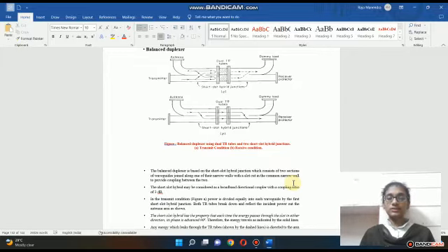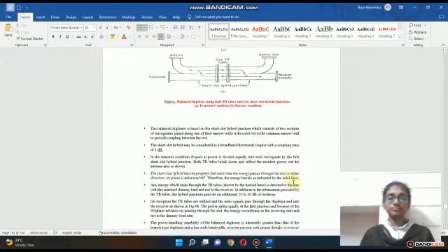In the transmit condition, power is divided equally into each waveguide by the short slot hybrid junction. Both transmit receive tubes break down and reflect the incident power toward the antenna, as shown in the figure. The short slot hybrid has a property: each time energy passes through the slot in either direction, its phase is advanced 90 degrees. Therefore, the energy is indicated by the solid lines.